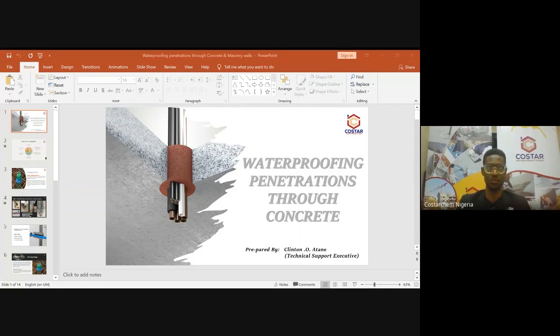Once you've done the opening, the next thing you have to do is the surface preparation. You prime with an adhesive, a bonding agent, and a product that's well fitted for this is our Coastal range of bonding agents, which is our Super Bond 20, which is epoxy based, and Aqua Latex C10, our Super Latex as well. This also falls into the range of bonding agents that can be used in this category.